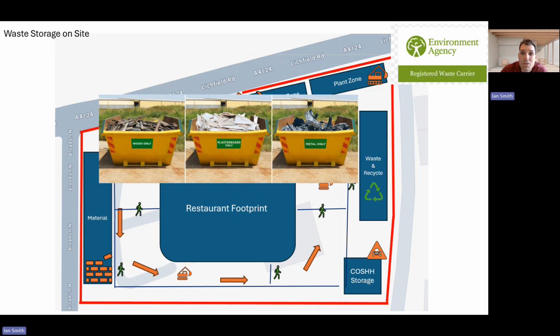There are some opportunities for recycling. For example, excavated soil may be used on site for landscaping or backfilling, or used on different projects for these purposes rather than being removed as waste. Metals, timber and plastics can also be separated and sent to recycling facilities or reused on site instead of landfill. This helps us to conserve our natural resources and reduce our landfill use.